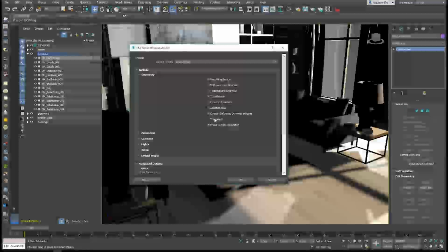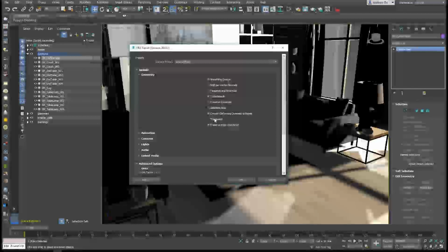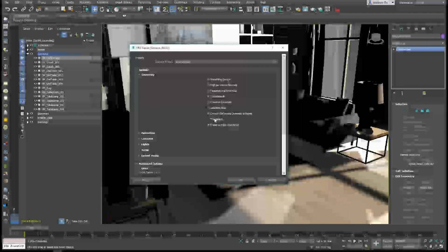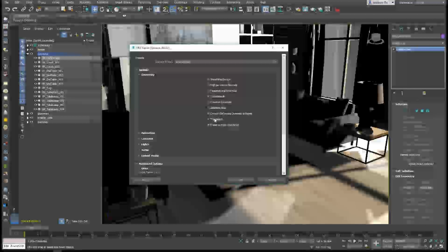You don't have to do this one here because Unreal basically automatically turns every mesh into triangles. And even though technically all 3D meshes are in fact based on triangles, sometimes when you build them, obviously you might build them with quads, four-sided faces instead of triangles. And this will just automatically turn those quads into triangles for us when we export.